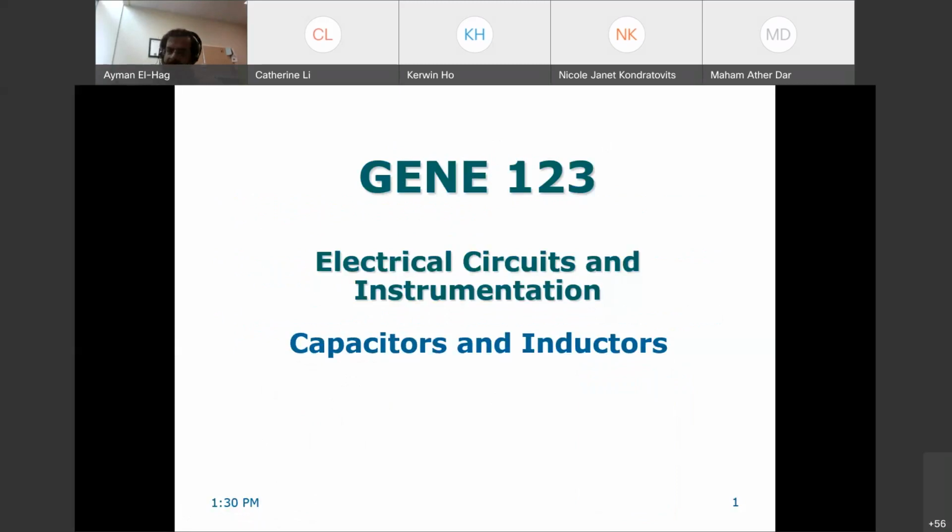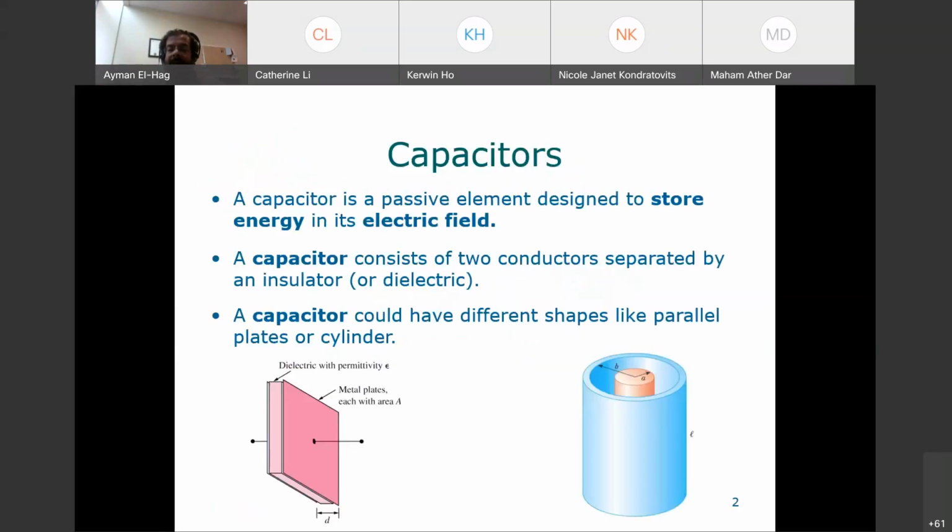One thing is the following. If I have a circuit, let's say I have a voltage source, and a resistance, another resistance, and a switch to switch the circuit on and off. Assume the switch was off. The moment I open the switch, immediately I is equal to zero, because the resistors, which are the only passive elements we learned so far, cannot store energy.